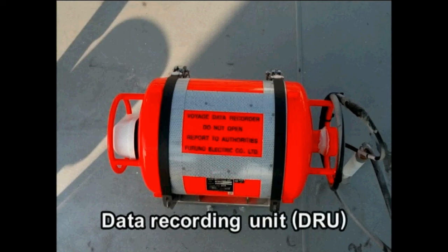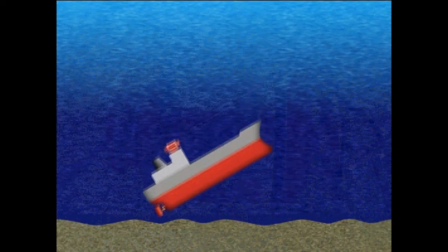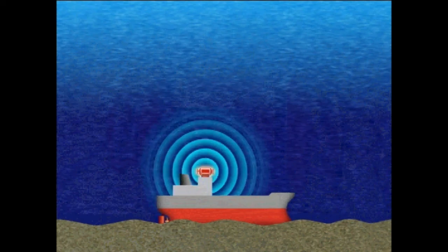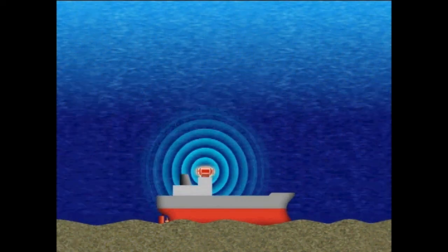The memory containing the recorded data is kept in a protective capsule. The capsule can survive hydrostatic pressure equivalent to 6,000 meters of water depth. It transmits its position using an underwater sound beacon for a period of 30 days.